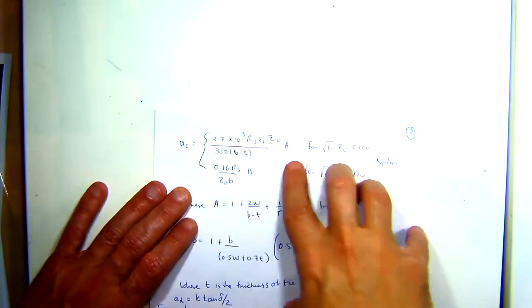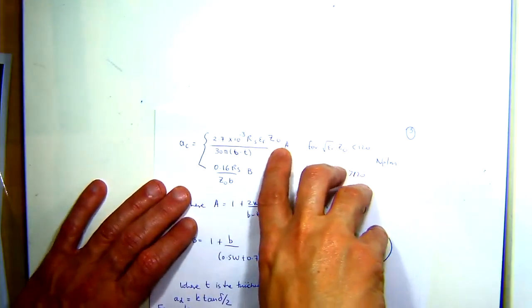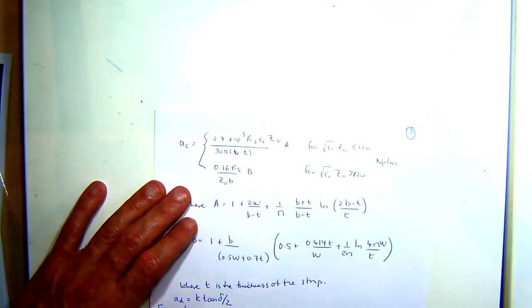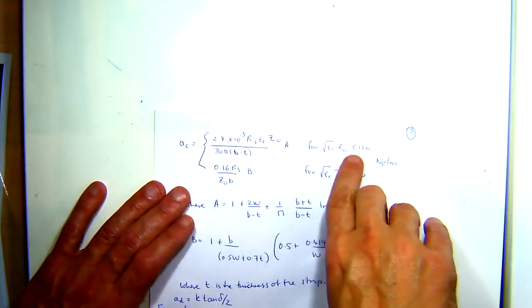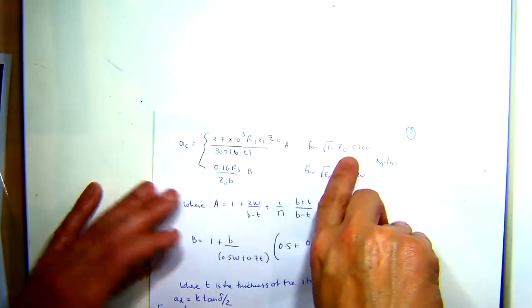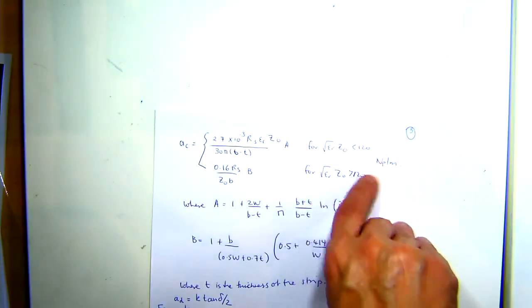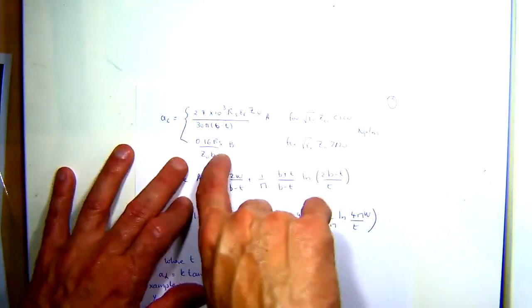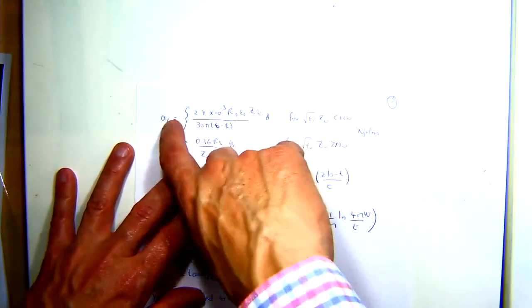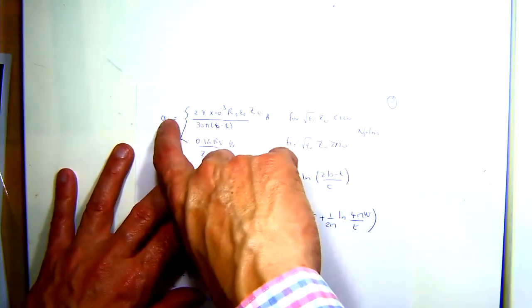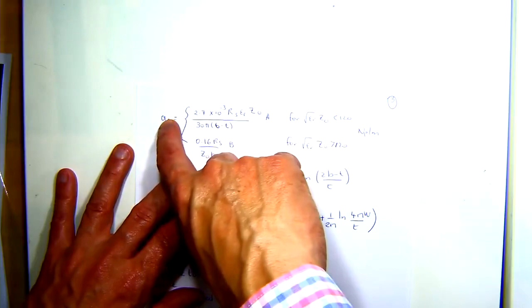So here, if I said to you make a 60 or 70 ohm line, what you would do is say, all right, 60 ohms on FR4, it's greater than 120, so therefore I'm going to use this formula, and that's how I'd calculate my conductor loss, right?